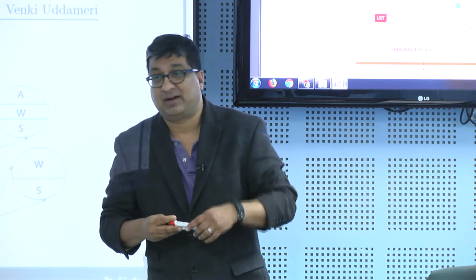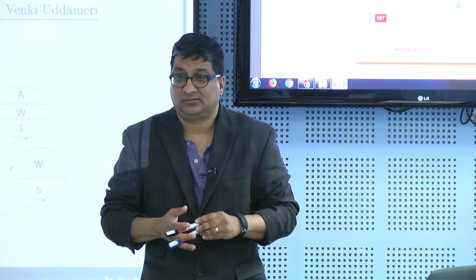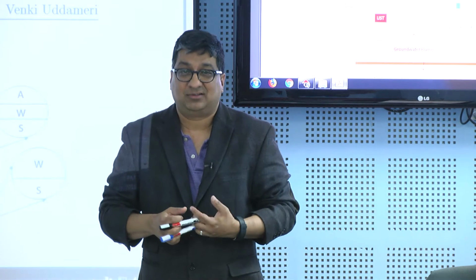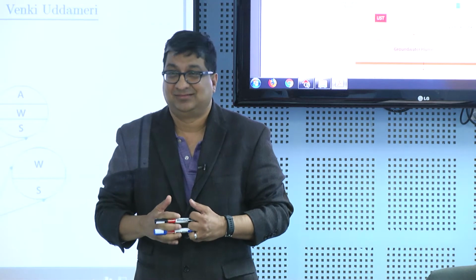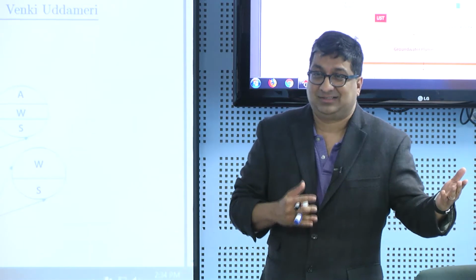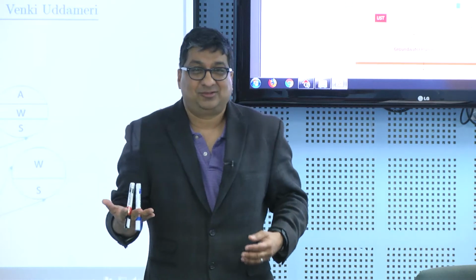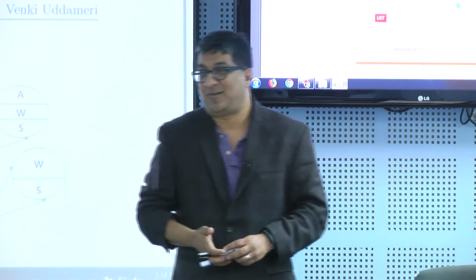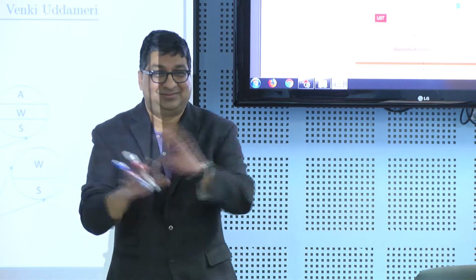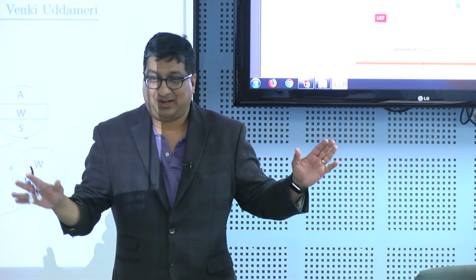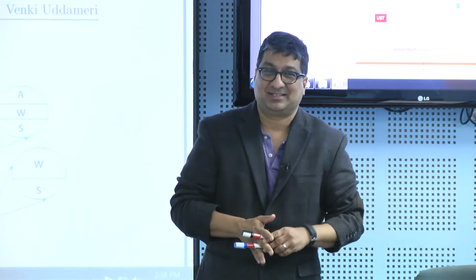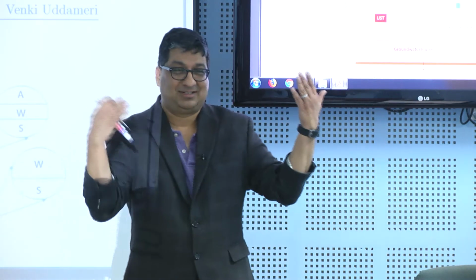If you're environmental engineers, you know reactors, right? How many of you are civil environmental people? So you all know what reactors are. If I look at an aquifer, is that a batch reactor? Is it a completely mixed stirred tank reactor? Is it a plug flow reactor? What could it be? Batch reactor means there's no flow. We can rule that out because there is flow. If it was a static system, then that's a batch reactor. So it's not a batch reactor. Is it a completely mixed reactor, or is it a plug flow reactor?